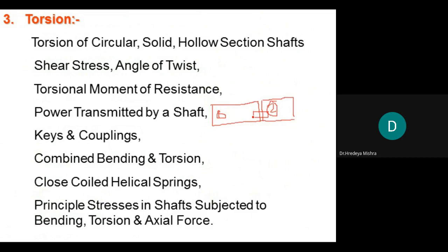If two shafts are connected via the key, then both shafts have a keyway or key slot where the key is fitted. This key is required to transfer or transmit the power or motion from one shaft to another shaft. The same work is done by the coupling.